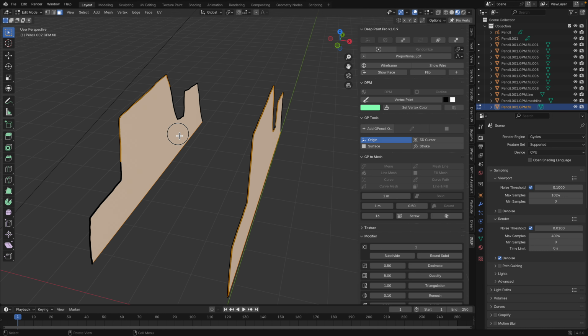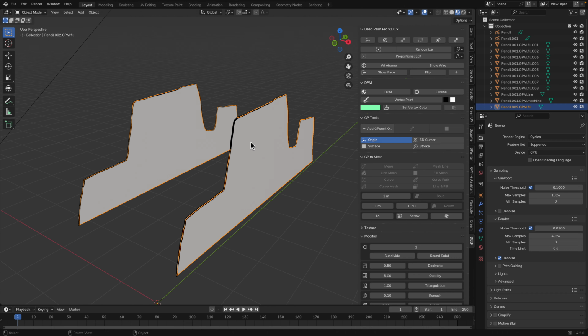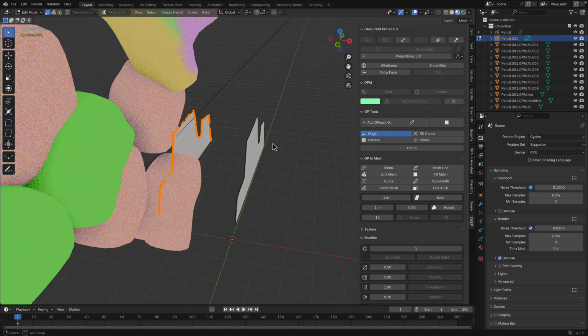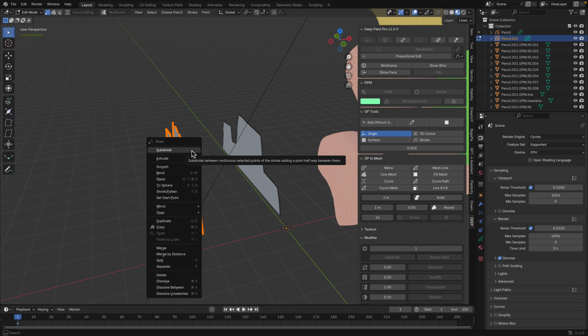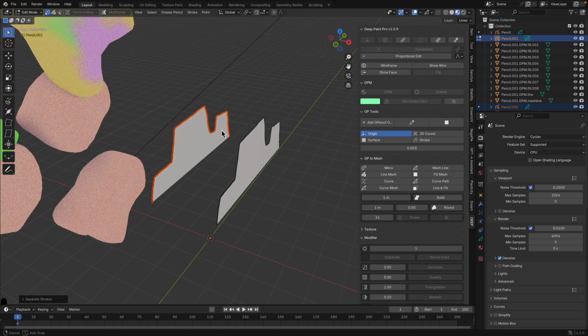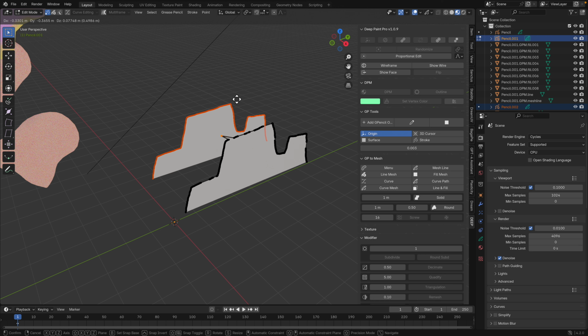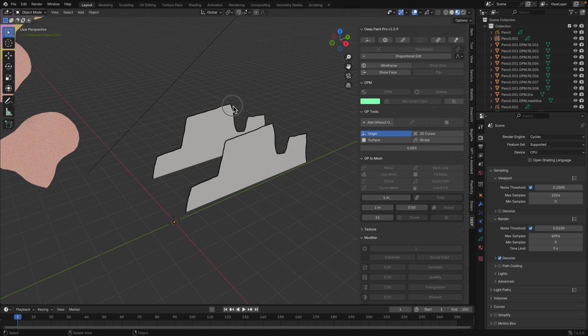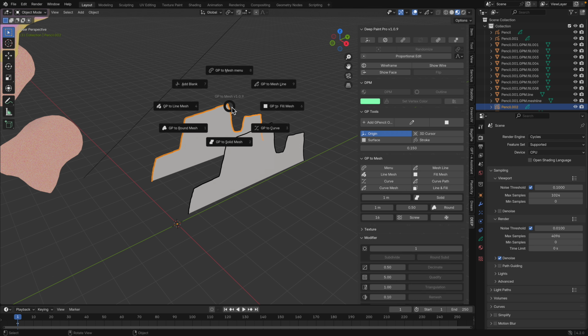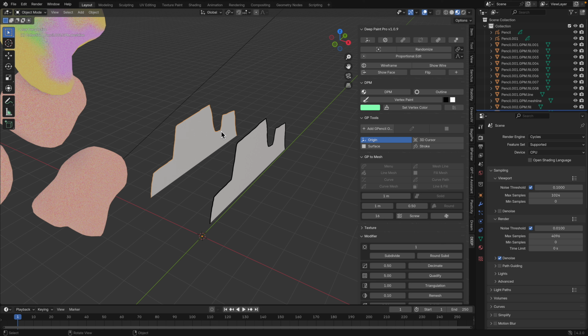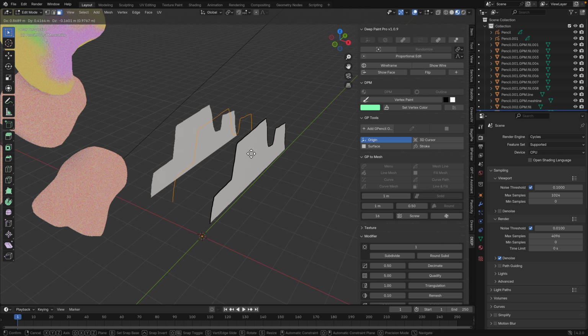We can connect these two together, because this is already like a stroke object. Let me select the stroke and then separate by selections. So we have this object over here. We can right click and then use E and convert it into curve or mesh line. Okay, mesh line is very useful because we can just extrude.